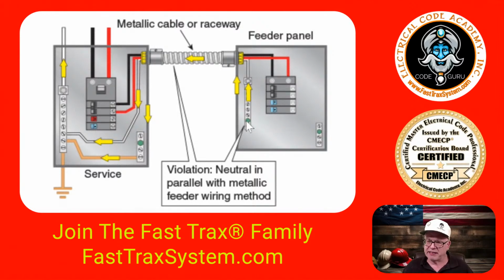This is prohibited. Not only does it create objectionable currents, meaning, as we talked about earlier, if there is any neutral current traveling back to the source, it's going to travel back on the neutral, but some is also going to be traveling back on the metal parts. Now, it's all proportional to the impedance of that path. So obviously more current's going to travel on the white conductor than the metal enclosure. But when it comes to touch potential, if you have a poor connection for that neutral, then more current's going to travel on the metal parts and it creates that touch potential. And we're not supposed to be intentionally putting current on the metal parts.